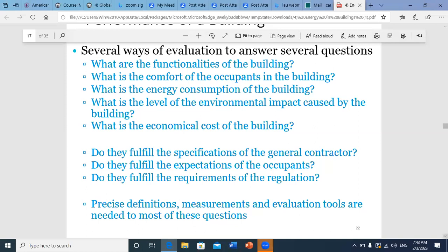Now, the energy consumption of the building also is very important to know, in order to assess what are the strategies to be implemented. Whenever you want to include renewable energy, to size your solar system, let's say you want to use PV, the number of PV arrays you should use, PV panels, what are the batteries needed for energy storage, etc.